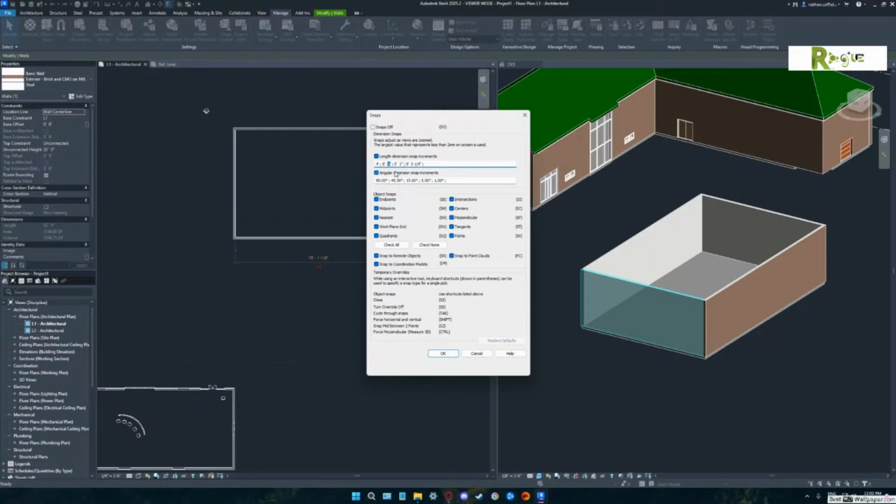Yeah. Also, if you notice on here, do you see next to the endpoints it says SE? That means if we type in SE, we will snap to an endpoint. And if we type in SM, we will snap to the midpoint. And by default, all of those things are going to sort of try to automatically snap. It tries to read your head. But the big one is that nudge at the top. It also happens when you're drawing.